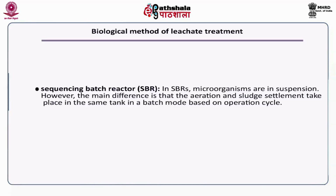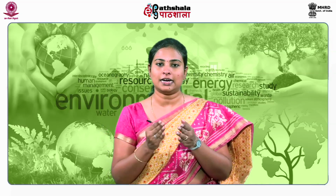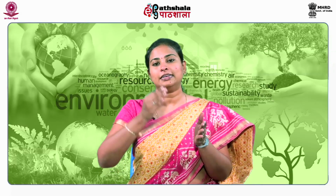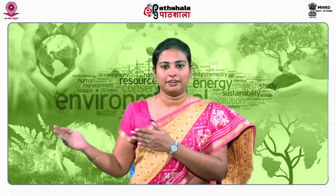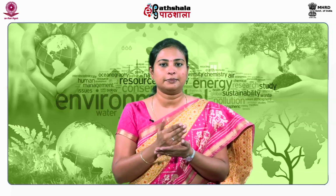The next type of reactor used for leachate treatment is the sequencing batch reactor. In the sequencing batch reactor, the process occurs in a single unit in a series. It has 5 different phases: first fill, then react, then settle, then decant, and then idle. These are the 5 different phases that occur in a sequencing batch reactor.